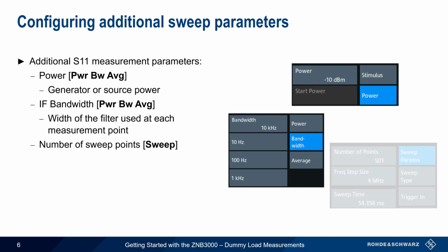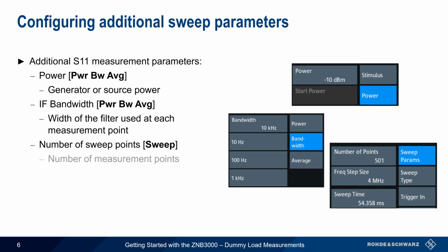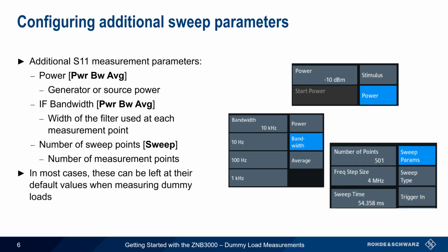And the number of sweep points can also be changed. This is the number of discrete measurement points within the defined frequency range. Note, however, that in most cases, these parameters can be left at their default values when making measurements of dummy loads.